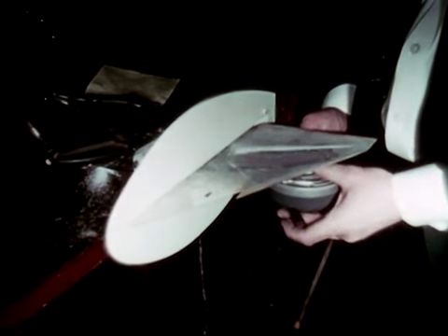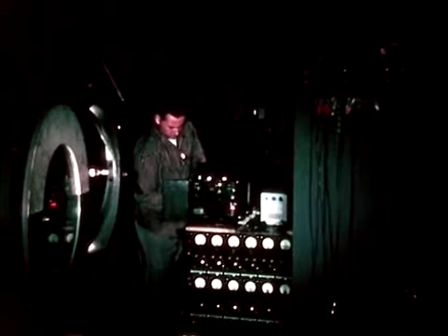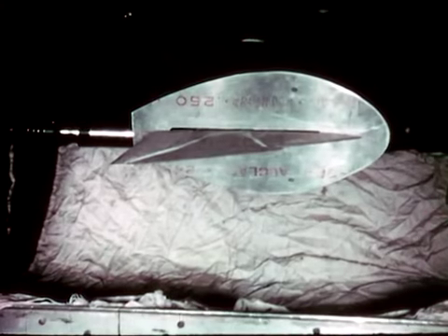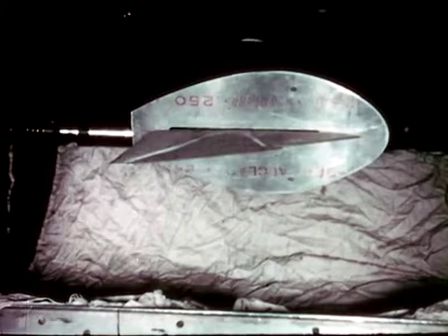An air shaker was used to excite the wing modes for damping measurement before installation in the tunnel. The model was then installed on the tunnel sting, the strain gauge recording equipment connected, and the tunnel prepared for a test run. The first model showed no flutter, and weaker models were tested to establish the flutter boundary.